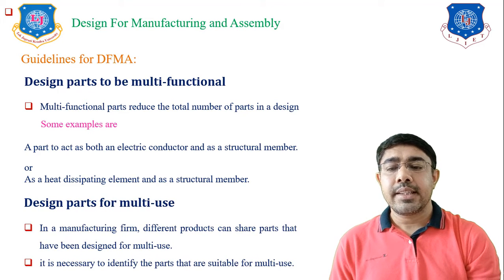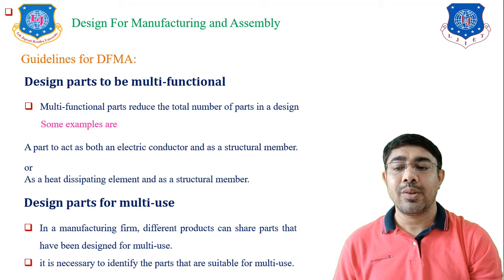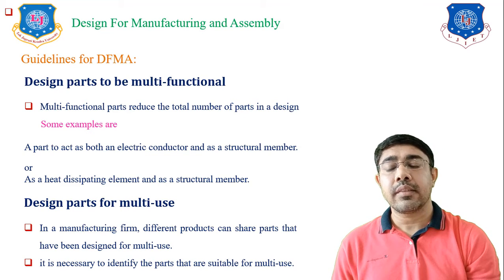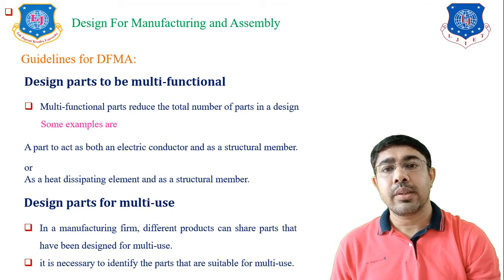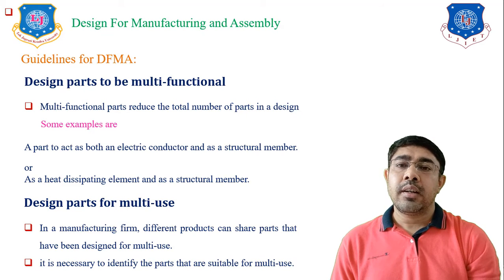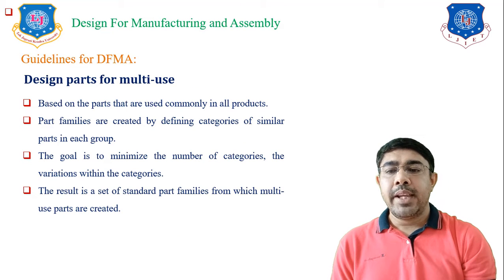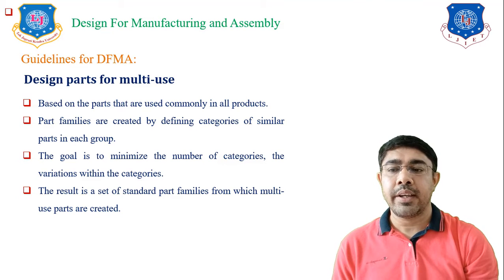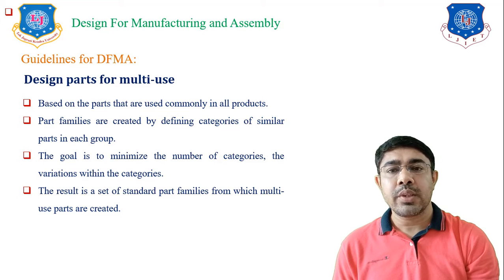Now next guideline is to design parts for multi-use. As we use multifunctional components, we also consider parts for multi-use. In a manufacturing firm, different products can share the parts that have been designed for multi-use. So we have to identify the multi-use components, based on the parts that are commonly used in all products.